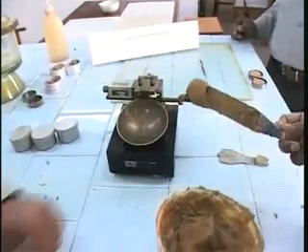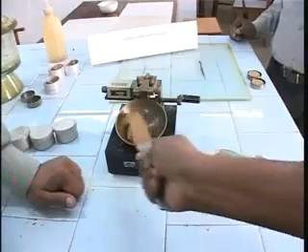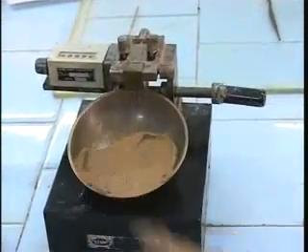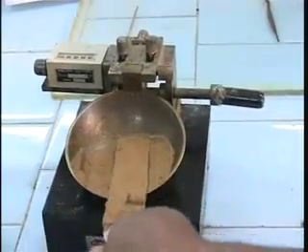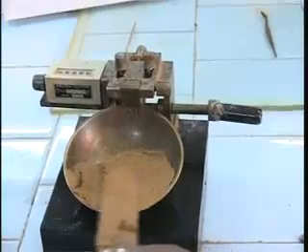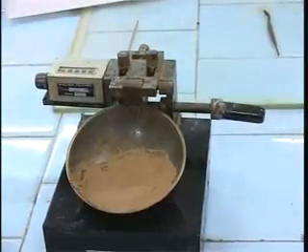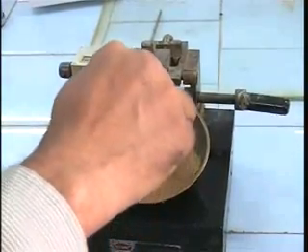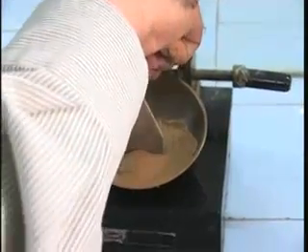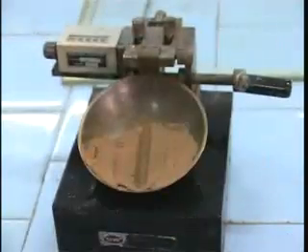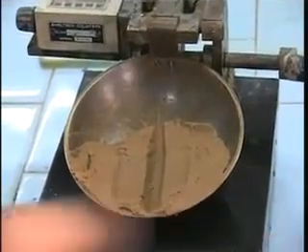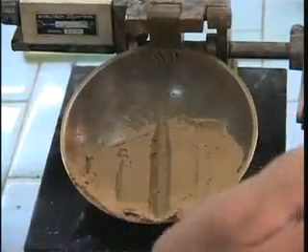Okay, so now we begin. Okay, so you see now we are preparing the pat in the pan, making sure that there is no air entrapment within the volume of soil, and the surface of this particular pat should be approximately horizontal, and then we use the grooving tool as you see here to cut a groove at the center of the pat, the clay pat or pat of fine grained soil, and this is the groove that we have constructed here using the standard grooving tool, and then we are going to bounce the pan up and down,